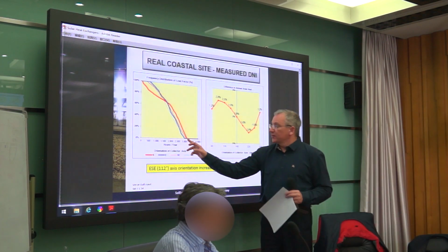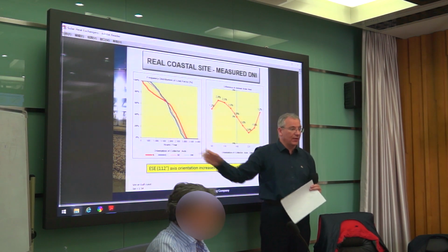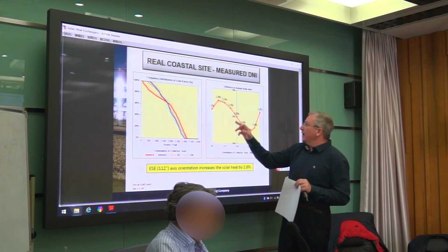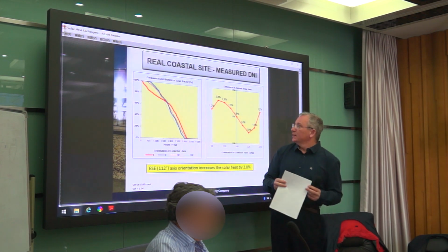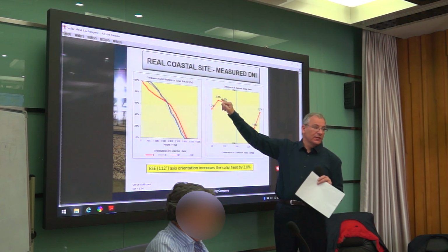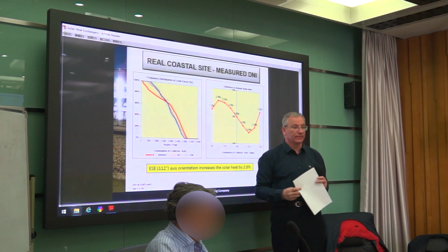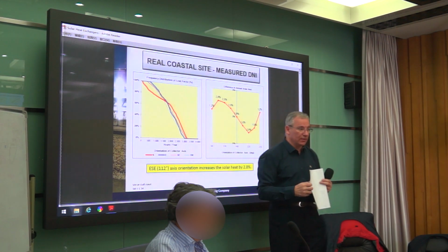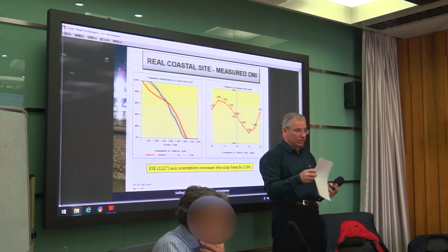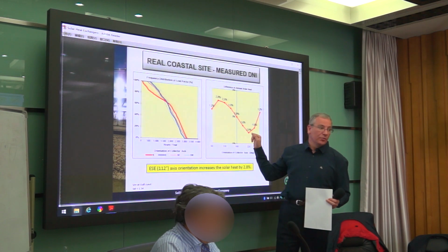Here we have the hours. For example, in this real site we have 3,000 hours when we can operate in this position, and over 3,000 in this position. And if we put it oblique, we can see that in the evening we get nearly 2.8% more energy from the solar field over a year than if it would be in this position. And even if we do it oblique on the wrong side, which is the risk for engineers, if you plot it on the wrong side,